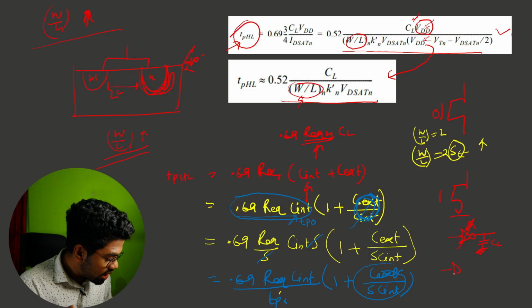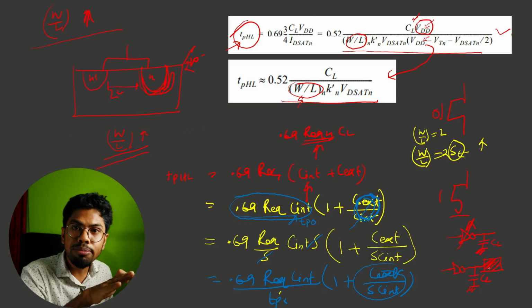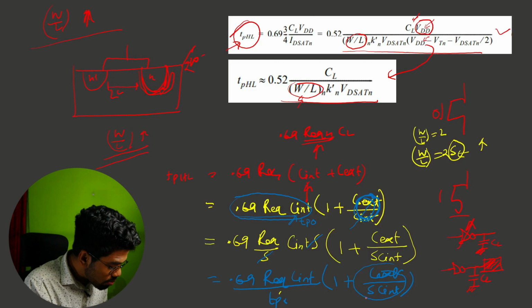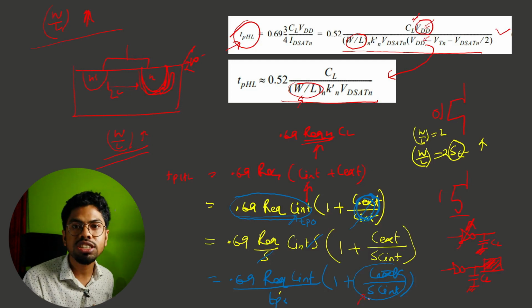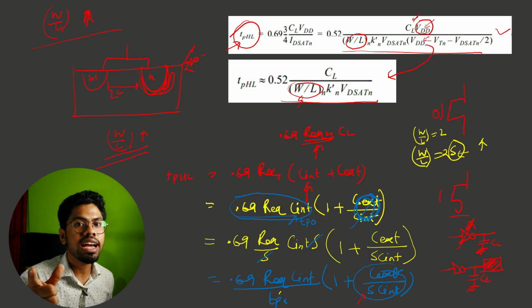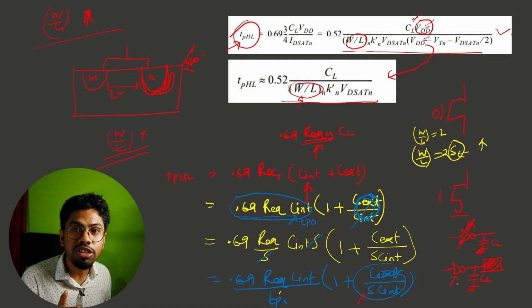But now in the case you have something here and then some other circuit here in the black box, then this CL is not only due to your internal capacitance but also due to the external capacitance given by that circuit, that black box. That time you might have some reduction in your delay if you size or increase the size of your inverter, of your input inverter.